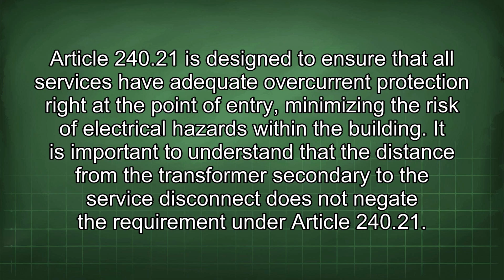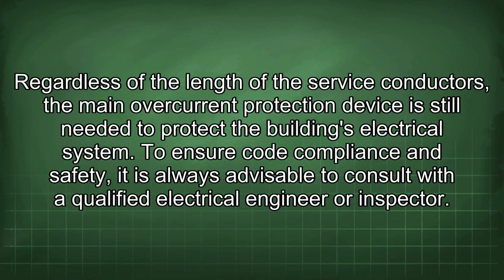It is important to understand that the distance from the transformer secondary to the service disconnect does not negate the requirement under Article 240.21. Regardless of the length of the service conductors, the main overcurrent protection device is still needed to protect the building's electrical system. To ensure code compliance and safety, it is always advisable to consult with a qualified electrical engineer or inspector.